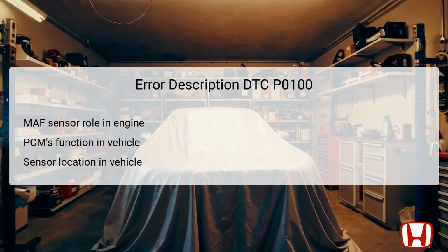The mass airflow sensor is crucial for engine management. It accurately detects the volume of air entering the engine. This information is sent to the Powertrain Control Module, PCM, which adjusts fuel injection timing and duration to optimize the air-fuel mixture. The PCM is typically located near the engine bay inside the vehicle, and it interacts with several sensors, including the MAF and intake air temperature (IAT) sensors, to ensure efficient engine operation.